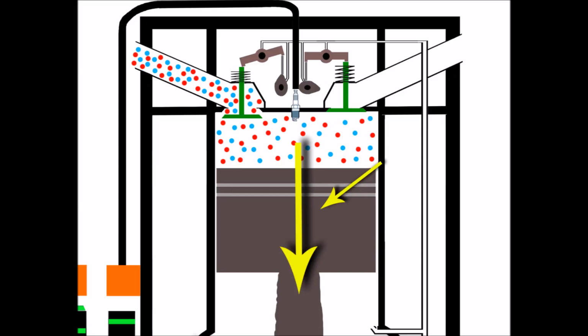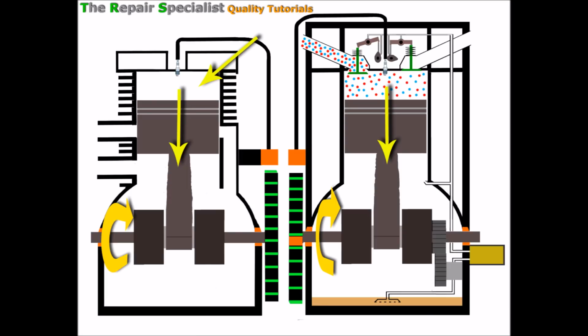So the piston continues to lower, and that continues to draw in that air and fuel on the induction stroke. And whilst all this is going on in the 4-stroke, there's a lot less activity here in the 2-stroke. If we look above here in comparison, we can see that there's no air and fuel coming in yet. And structurally, of course, it's very different. If we look at the top of the cylinder here, it's just a closed off cylinder at the top, other than the hole for the spark plug, which the spark plug's filling at the moment. There's none of this valving system that the 4-stroke has. So it's a lot simpler in this area in design.